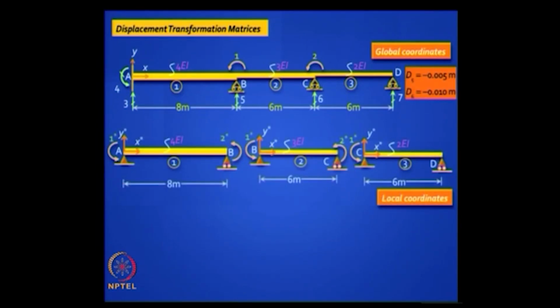These are our element level local coordinates. We have 3 elements, and for each element we usually have 2 degrees of freedom, except for the third element. The third element has 1 degree of freedom. Please pay attention. Okay, 1 degree of freedom, and you have to be careful about that. Okay, so please write down the transformation matrix. What will be the size of that matrix? It's going to look like this, at least get it right.